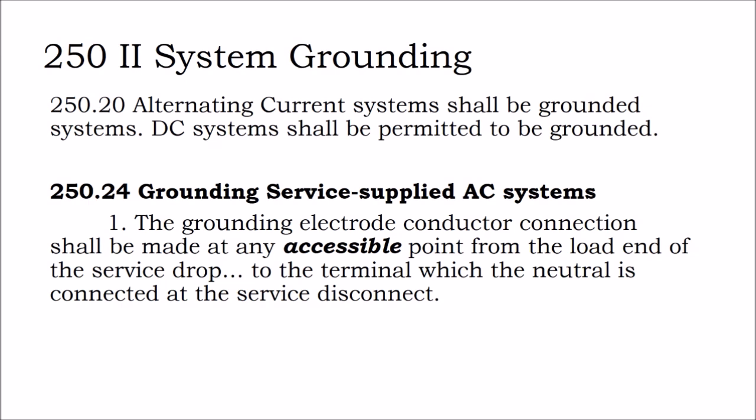It doesn't mean that it can't detect ground faults, but what it means is the DC side of the system is completely isolated from the AC side of the system. And that's actually safer, because if you do have a ground fault in the DC side, it doesn't impact the ground fault detection of the AC side, which was related to the blind spot in old style commercial inverters that were grounded inverters.